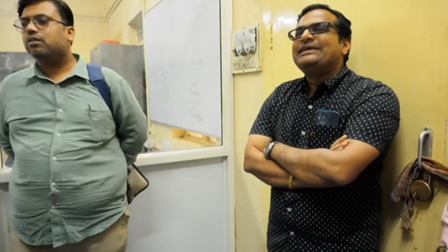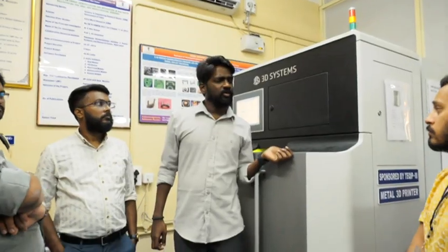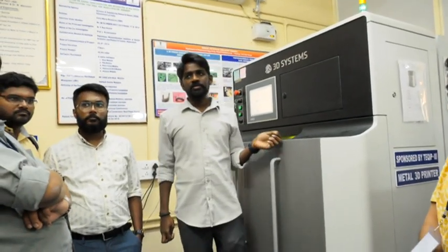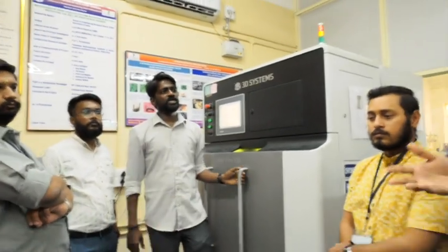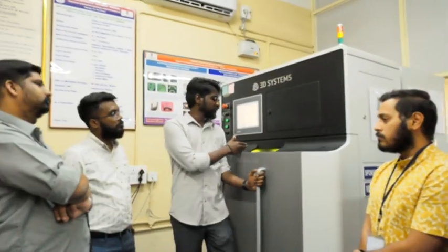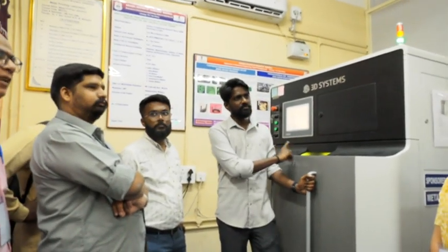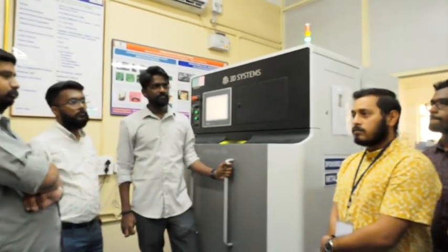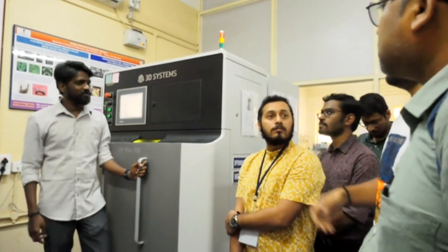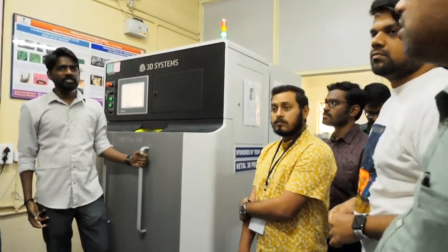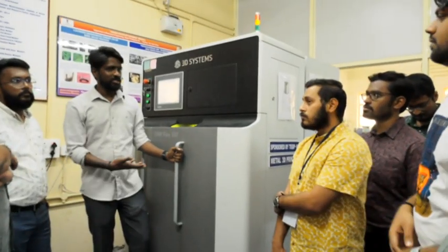So what are the base plate heating parameters that are available? Preheating, build plate heating regarding the substrate, do you have a provision for this? No, we are not preheating. Sir, the build plate temperature will be maintained at some temperature, like in the US machine, after starting it goes to preheating, around 80 degrees, automatically. So preheating is done automatically by the machine. Actually, in EOS cases it will be directly maintained at 200 or so. It depends on the machine. Yeah, that's what I'm asking: is there any provision? No, not right now.